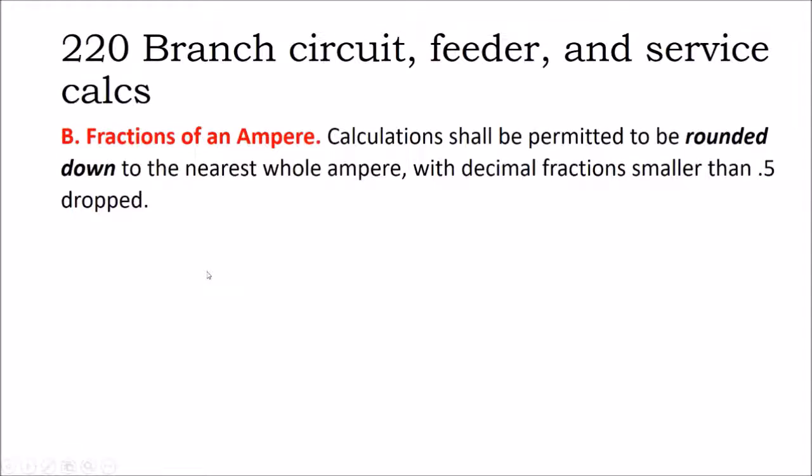We see these 25% additional correction factors. We'll see temperature correction factors come into code that are all erring on the side of caution. And so by the time we get to the final decimal and rounding, the system says, all right, any fractions of amps, just round down.